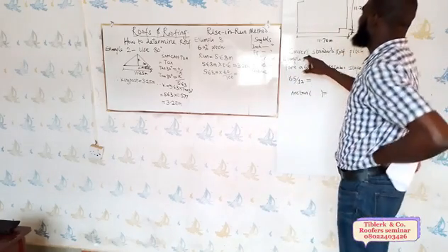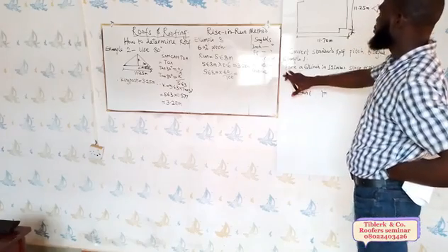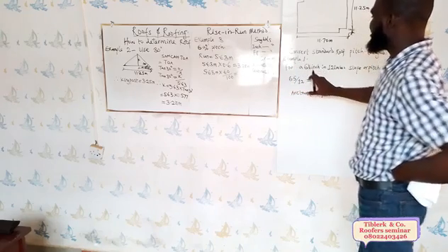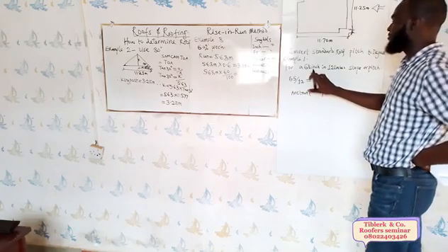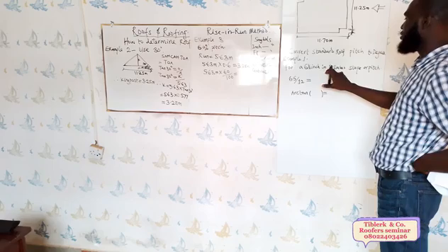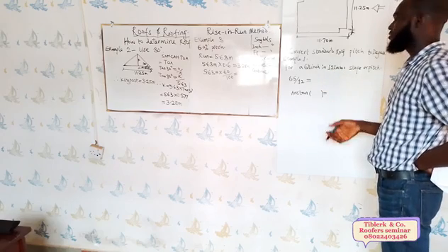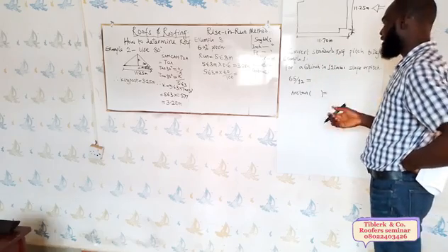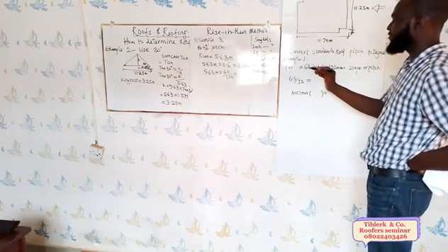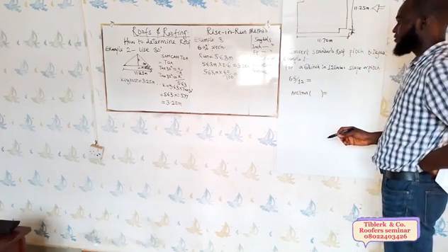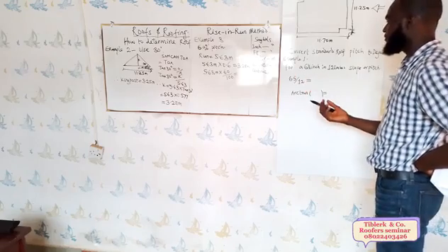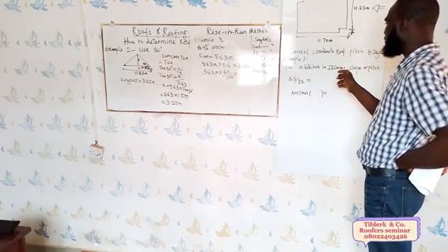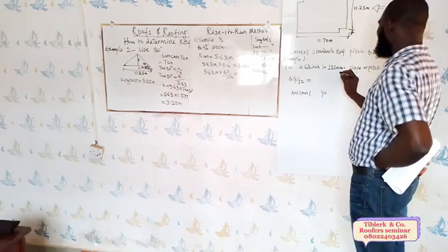Now, we want to convert this. Let us assume that we are given this rise and run, 6.5 inches in 12 inches, slope or pitch, and we now want to convert it into degrees. How do we arrive at that? Do not forget this is 6.5 inches. So we just need to divide our rise by our run.